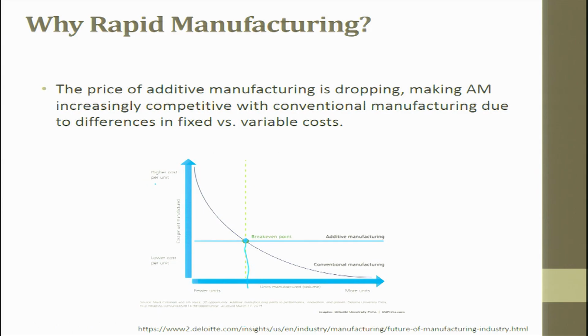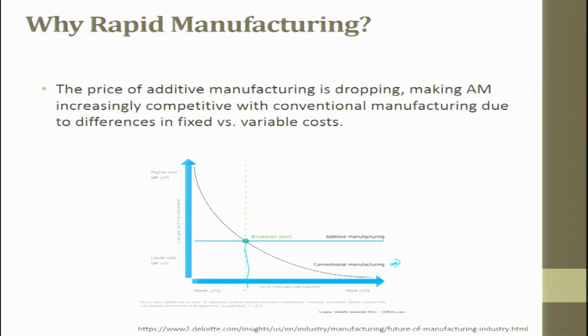Okay. So, this shows the higher cost, lower cost, the cost per unit manufacturing, and here it says unit manufacturing in terms of volume. Of course, when the volumes are more, conventional is the best method of making it. Conventional methods are the best, and especially sheet metal or metal forming operations. Nothing can be more economical than that. But if the quantities are little, you can't use the same metal forming techniques, because the die cost is pretty expensive. So, this is the breaking point which talks about additive manufacturing and conventional cost in terms of units.